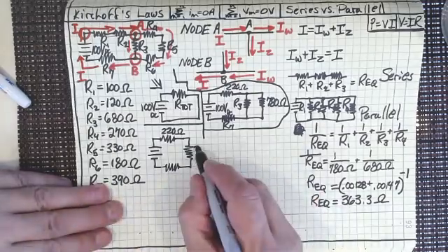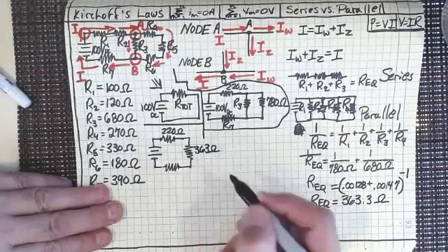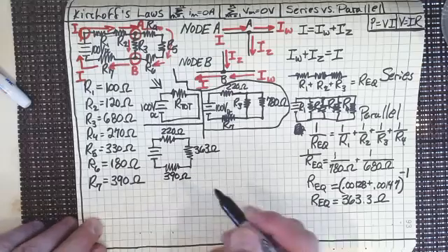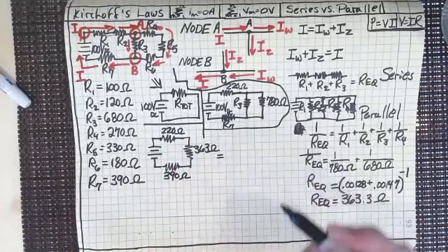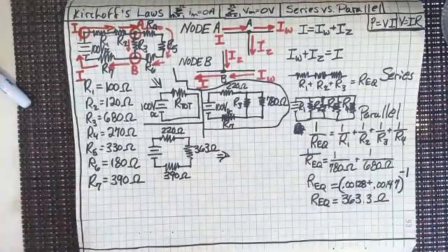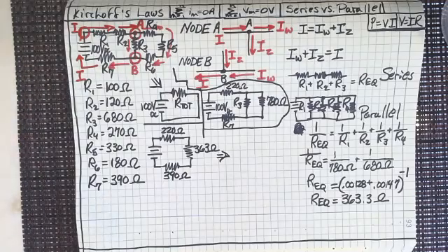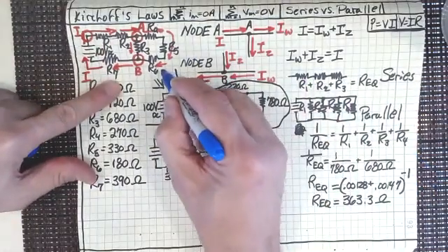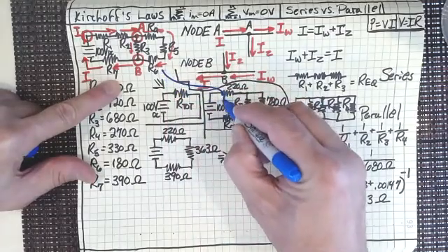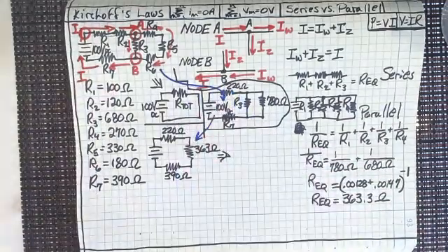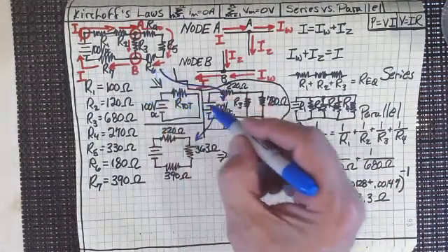So we now have this circuit. We've got a 363 ohm resistor, and on the bottom, R7, if you look, is 390 ohm. So now we've got 3 resistors in series, don't we? If I just wanted to come up with, I'm going to use another color here. Maybe blue would be a good color. So we really went from here over to here, down to here, right? That's the direction we're going in with the blue as far as simplification.